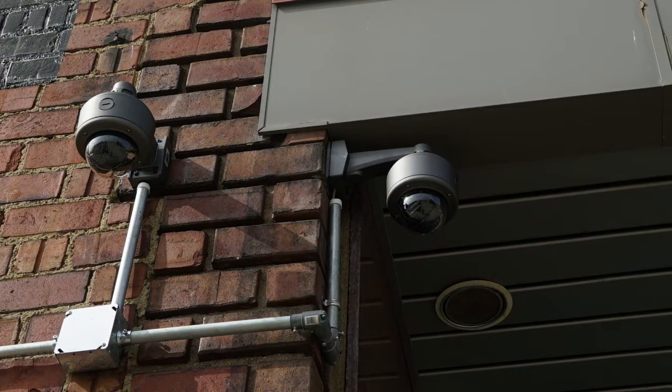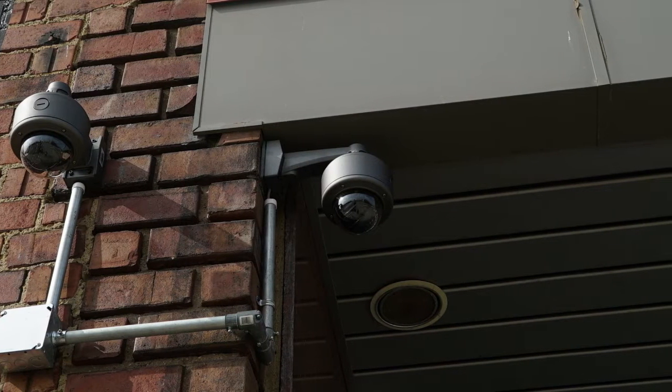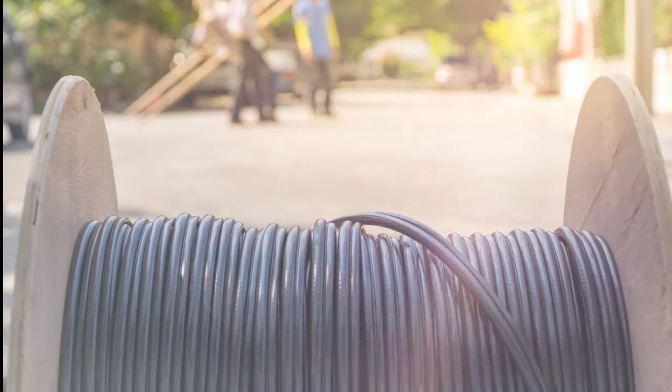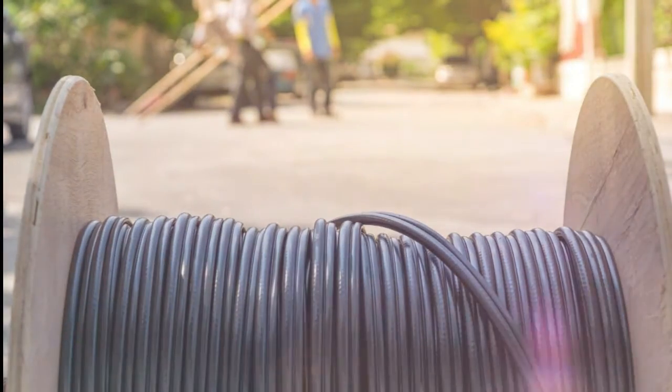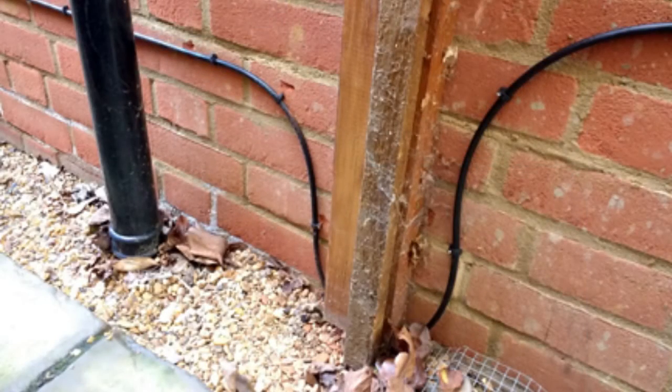This is against US nationwide building codes, and the AC power running through the power lines creates noise which can be induced into a video cable, causing poor performance. For external installations, do not run a cable so that it is directly exposed to the elements. The quickest way to a cable failing is to expose it to direct sunlight for a long period of time. The UV rays break the cable down and will degrade performance of the camera.